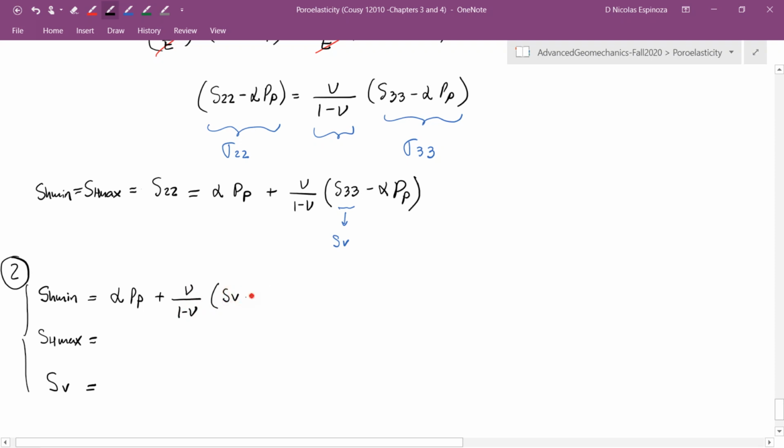Notice that so far it is the same as what I have in the equation above, but now I have to add the component of the tectonic strains, where this is going to be proportional to what is known as the plane strain modulus, and this is going to be times, in this case, the tectonic strain in the minimum horizontal stress direction plus the Poisson ratio times the tectonic strain in the maximum tectonic stress direction.